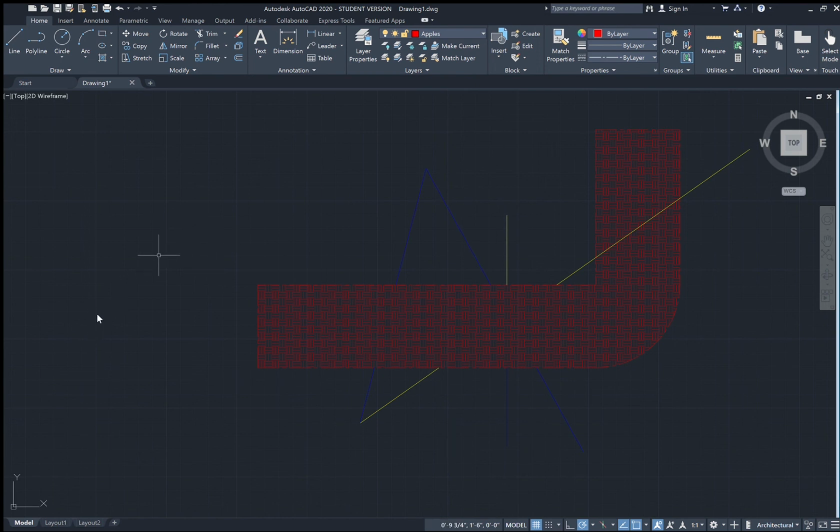as you can see, we have all these different cells with all this different information. The Properties tab lets you select any object in your drawing, and it'll tell you everything about that object: what layer it's in, the line weight, how long it is, truly anything. If we were to select this line, for example, it says this object is a line.